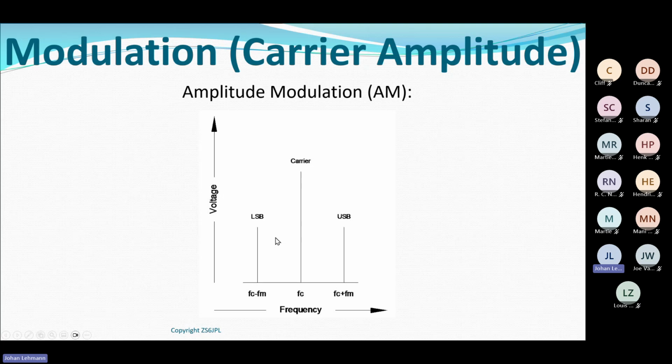Of the third that remains, the lower sideband and the upper sideband are a mirror of each other. In other words, the audio signal that is modulated on the upper sideband side and on the lower sideband is the exact mirror of each other. So of the third that's left over, half of it is also wasted, fruitless and wasteful expenditure, because it doesn't add value to my signal. So that's why amplitude modulation is not a very popular method in amateur radio, because it's wasteful.